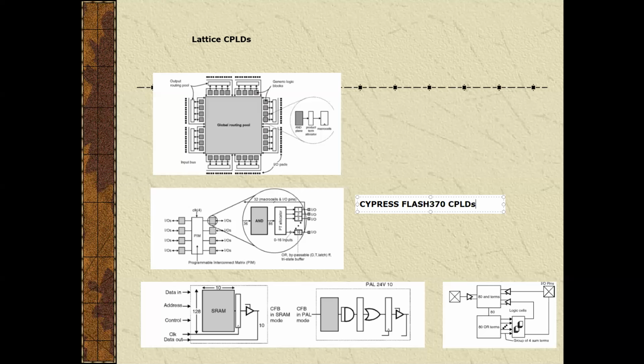Within each PAL block, there is an AND array that feeds a product term allocator, and this illustrates another type of flexibility available in PAL-like blocks in CPLDs but not present in normal PALs.